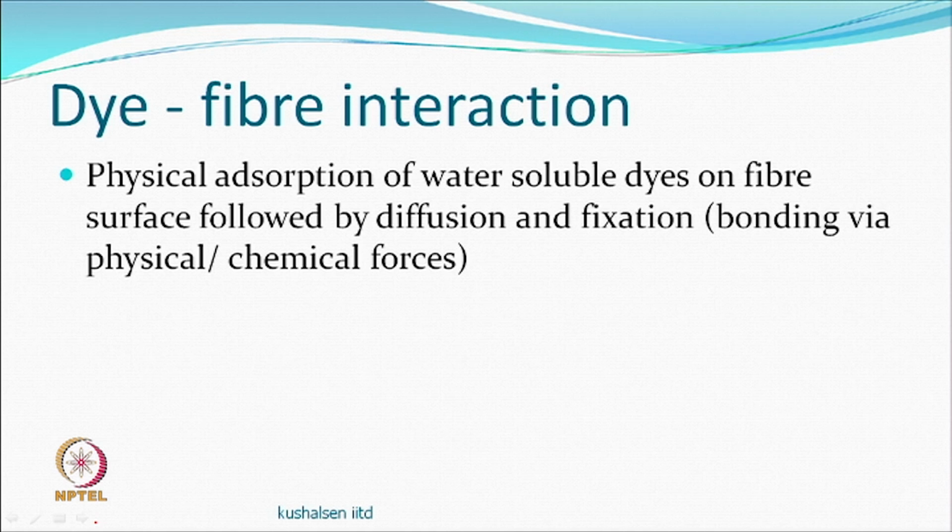In a normal case, the dye goes from solution to the fiber surface, and that is governed by, shall we say, affinity forces, and once it reaches the fiber surface, then the diffusion takes place depending upon the temperature, agitation and such conditions. In printing, you have no scope for agitation. So, you only believe that the dye definitely likes the fiber, and therefore, it just keeps moving in, right. This is what is going to be more important.